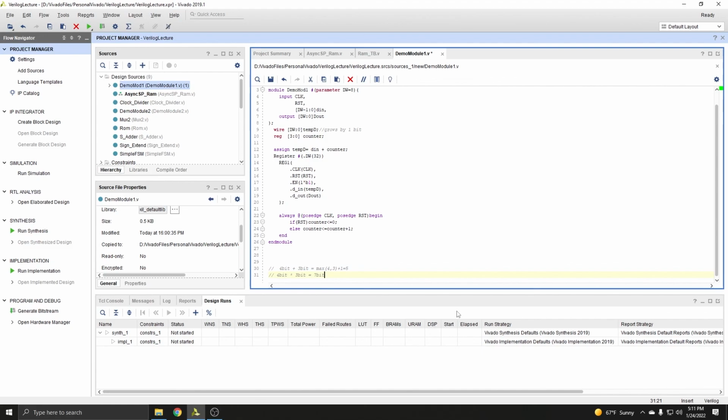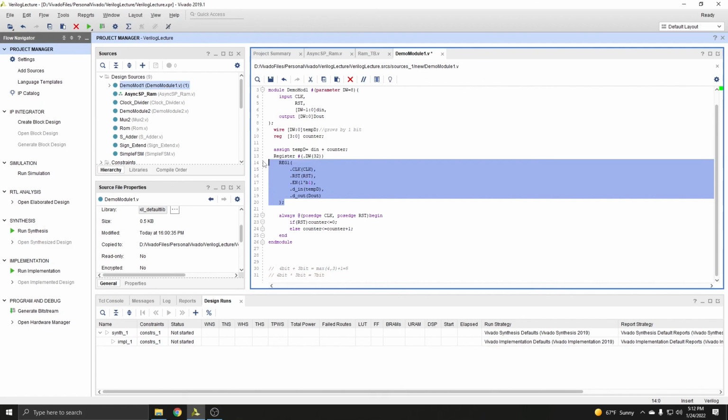There's a decent amount of work that goes into creating the single cycle processor. If you make all the modules first, test them thoroughly first, make sure they work first, then when you put them together, if you get any issues, then it's in how you put them together, because putting them together is a matter of just instantiating modules and connecting things together.